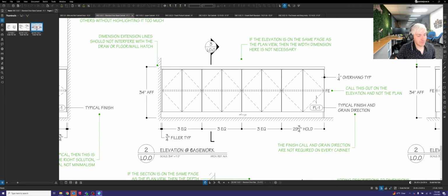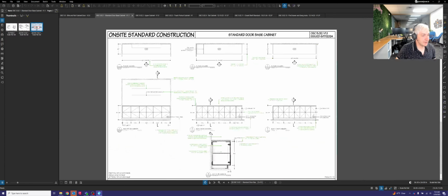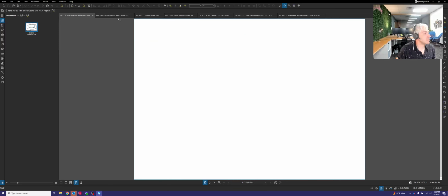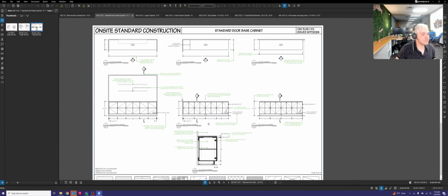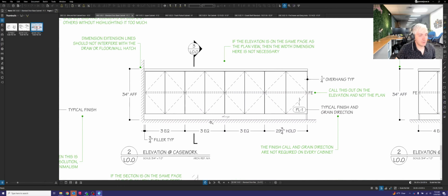Later on, we're going to talk about inside corner fillers, and those fillers are going to be a little different. They'll be wider than 3/4 of an inch, but we'll talk about that here shortly. So actually, why don't we just look at one right here if I can find one. Let me see if I got one in here. I might not. All right, so an inside filler is when you have two banks of cabinets that are coming together at a corner, a 90-degree corner.